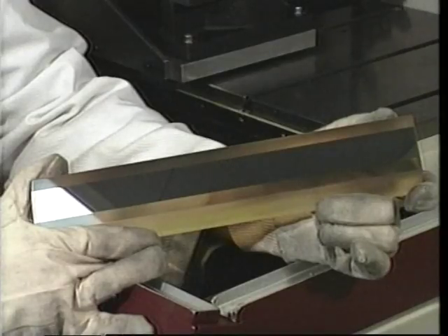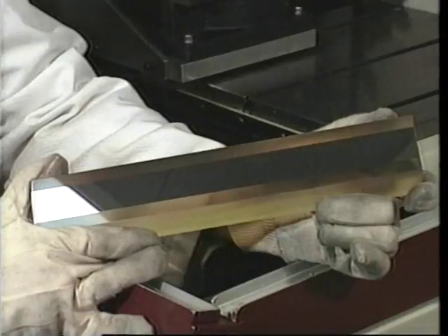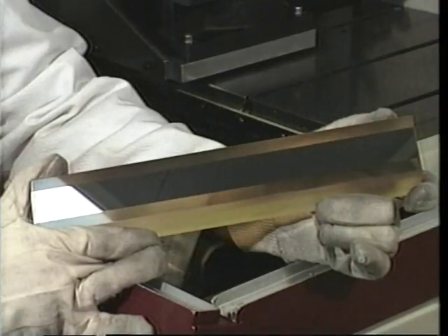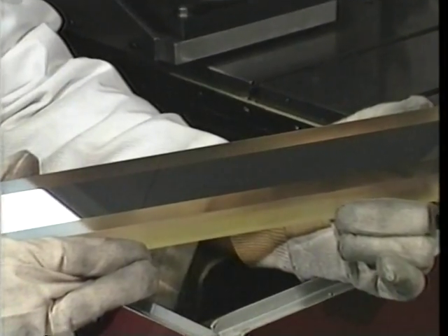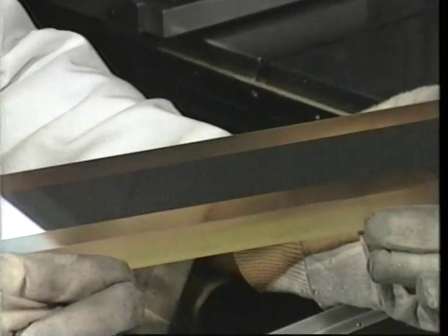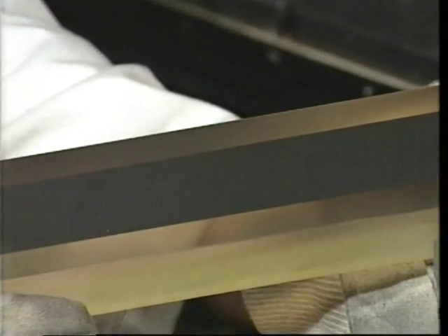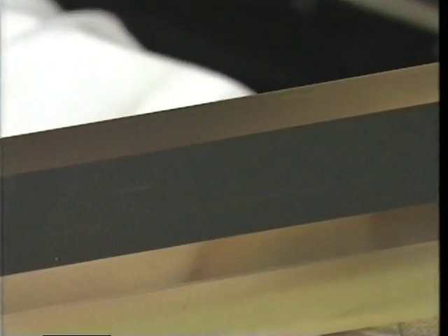As you recall from a previous lab, Zerodur is a glass material with a very low coefficient of thermal expansion, making it a very attractive material for high-precision applications requiring dimensional stability. The reference surface of the straight edge has been ground, lapped, and polished to be both smooth and flat. The error in the straight edge is specified as 45 nanometers over the 300 millimeters of length. The reference surface has been metal plated to facilitate use with a capacitance gauge.